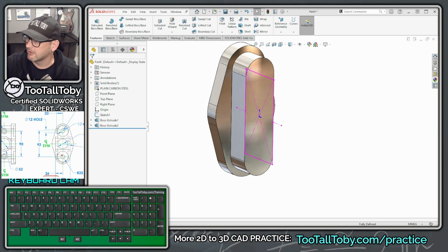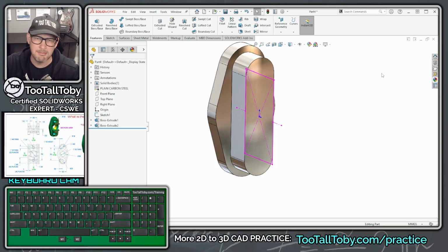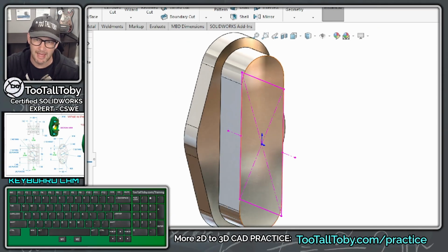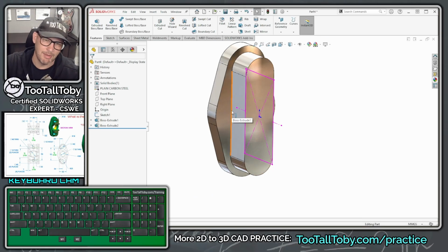And then same thing here, the depth of the other extrusion for the sleeve is just 22 off the mid-plane. So I probably don't need to create a layout sketch, but you could certainly consider doing that, especially if you were going to be mirroring some of that geometry. Like if you decided to only create the front half of this model and then mirror it, then you might want to consider creating some layout geometry again. I don't think it's necessary here. I think it might be overkill.